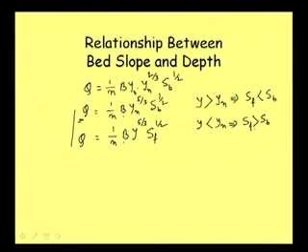Suppose the energy gradient line slope is reduced due to some obstruction, say we are reducing the energy gradient line slope. Then in that case depth will have to increase, flow will get retarded and depth will start increasing. So, this is one important relationship that we need to understand, and with this understanding also we can analyze the characteristics of gradually varied flow.